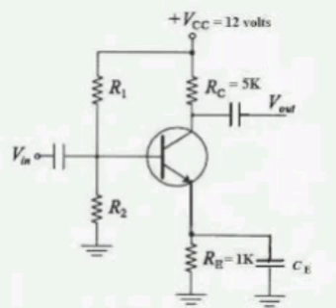Now applying, 10 amperes minus 8 amperes equal 2 amperes. R equal to 25 into 20 by 45, that equal to 11.11 ohms. So V0 equal to 2 into 11.11 by (100 plus 11.11) into 100, that equal to V0 equal to 20